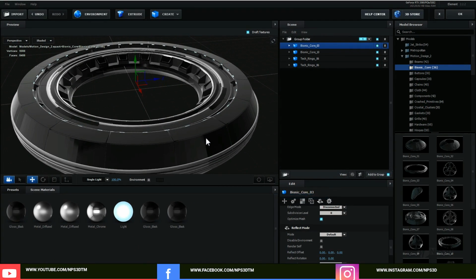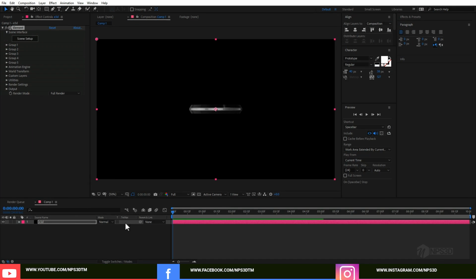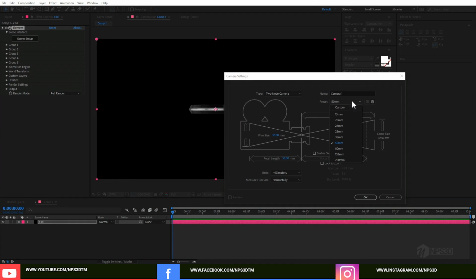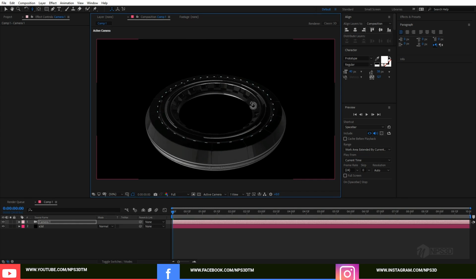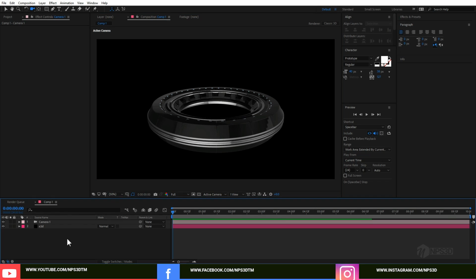So I'm going to remove unused material, right? We can also do texturing a little bit later. Let's hit OK and bring out a new camera, and I'm going to use something around 50 mm, which is also good, but let's change it to 24 mm, and we can also change it later if you want, and scale it, right? So you can see a little bit of the base, right?